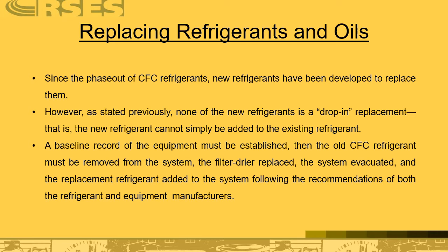I will tell you this, you're going to come across a lot of R22 equipment that is older in nature, typically 20 to 30 years old. It is frankly better just to change out all the equipment than try to convert to another alternative refrigerant because of the age of the equipment. I always tell my customers that retrofitting no longer makes sense.